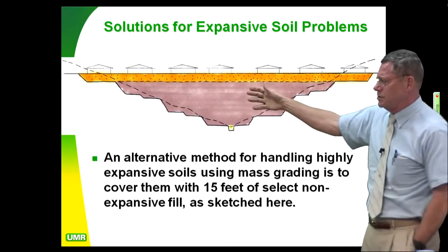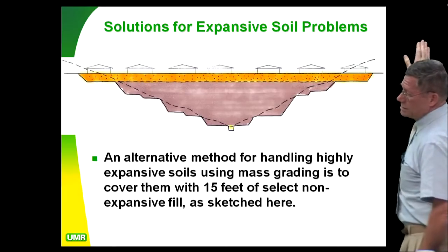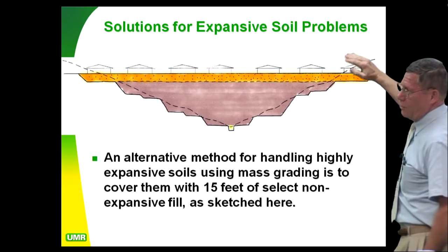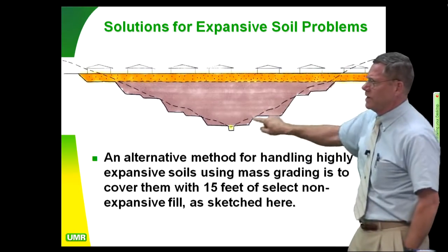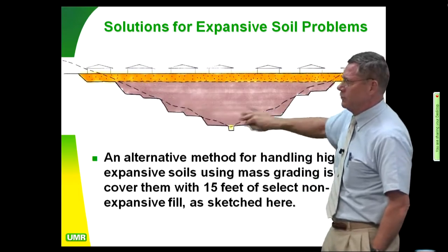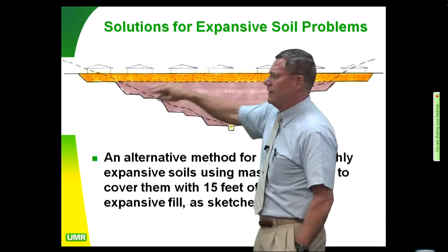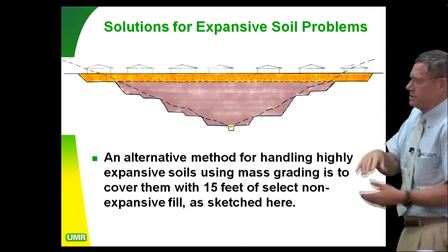Now, this kind of solution can work well for you if you're taking the soil-type material out, hogging it out first, and filling in the valley bottoms with that. But you have to over-excavate the bad materials out of here, the clays that are down here. You have to over-excavate those out and then roll them back into this thing so you don't cause consolidation of those materials.